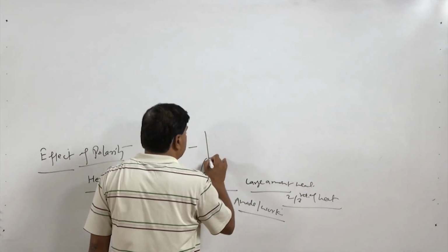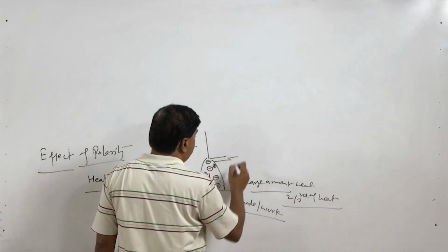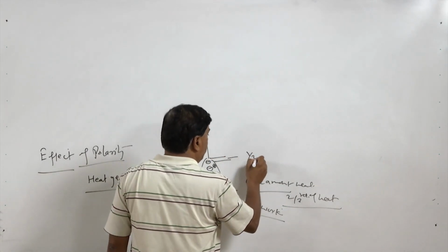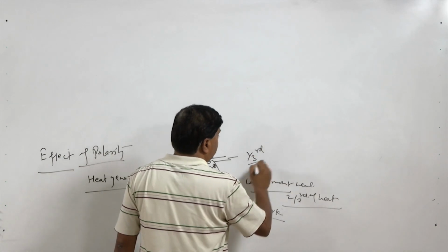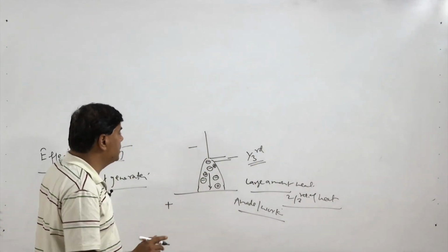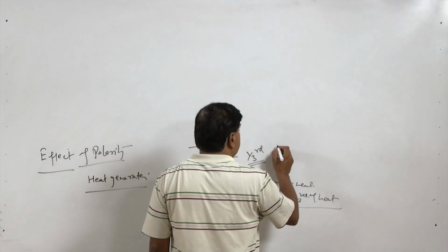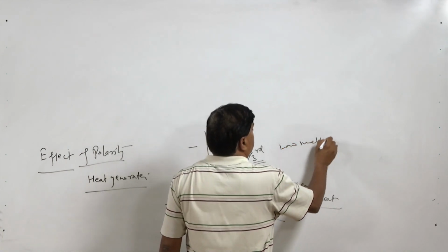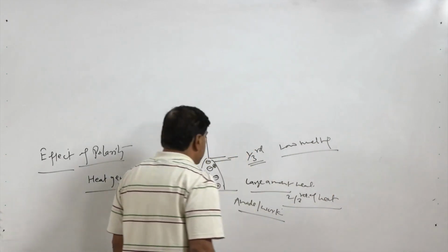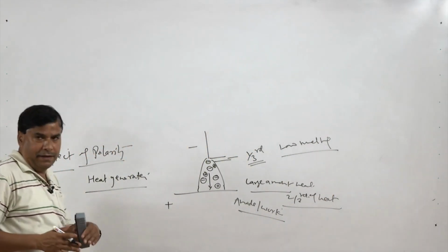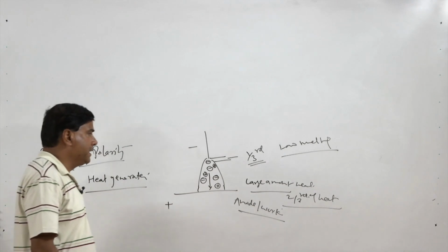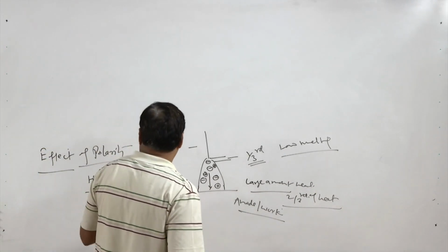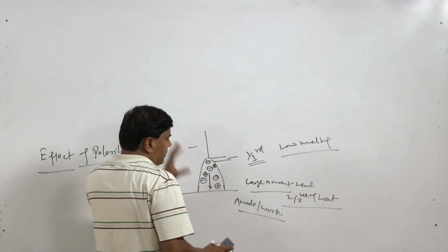So, heat generation in the electrode side or in the cathode side is very limited, it is about 1/3 of the total arc heat. So, limited heat generation will be causing the low melting rate in case of the consumable arc welding process, or it will be leading to the much better life of the electrode for the GTAW process. So, this is about the heat generation.